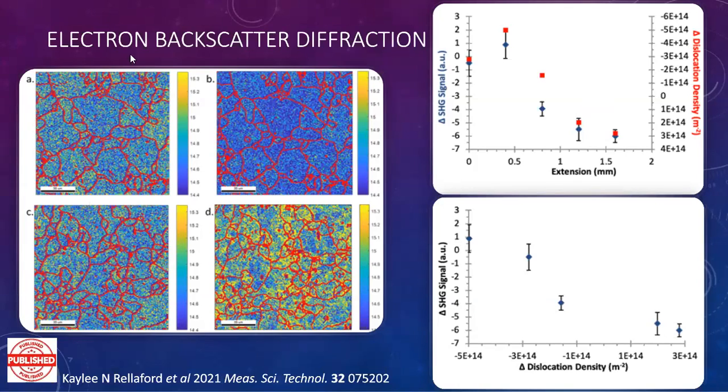The reason that the coloring changes is because we believe there's a little bit of an annihilation of dislocations happening from the heating that our laser causes. But the amount of change we get in C and D when we pull from no pull to 1.6 millimeters, which is our furthest plastic deformation, changes way over the small laser annihilation we may be experiencing.